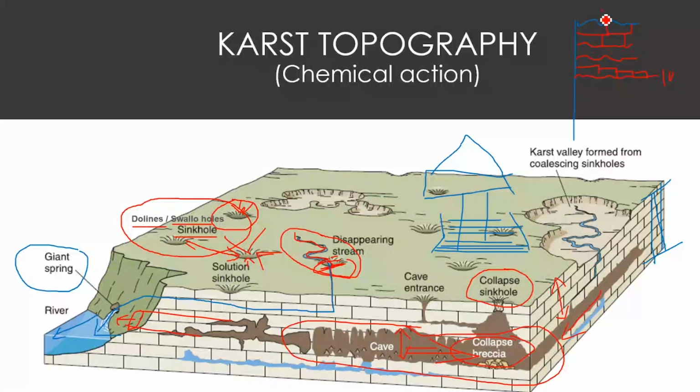But if you see the top of the cavity or the opening, this much depth is safe, okay, but the construction of a building at this surface is not safe, because it may not be able to take this load, and this part can also generate a number of small cracks, and finally all these things can collapse into the opening here.